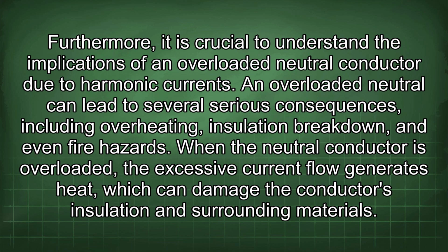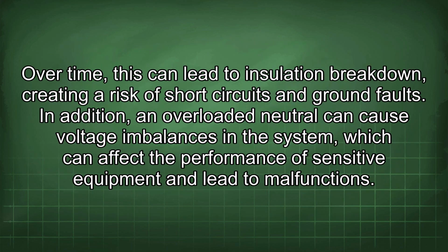An overloaded neutral can lead to several serious consequences, including overheating, insulation breakdown, and even fire hazards. When the neutral conductor is overloaded, the excessive current flow generates heat, which can damage the conductor's insulation and surrounding materials. Over time, this can lead to insulation breakdown, creating a risk of short circuits and ground faults.